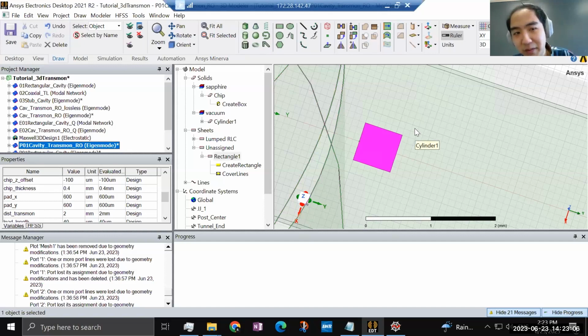Because as I said, HFSS only converges from run to run. And if the initial mesh already misses some charging effect on the edge, then it might converge to a wrong value. It can converge to, you can say, a local minimum without even capturing some edge charging effect. So in order for that not to happen, we want the meshing to be fine enough to capture these sensitive charging effects on the edge. But it might be very, very expensive to mesh the whole thing to that precision.